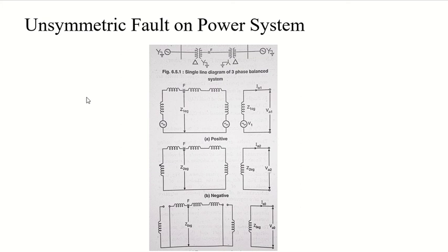All the faults we have discussed till now, I mean till the previous lecture, are easily analyzed by using Thevenin's theorem. This Thevenin's theorem is used to determine the changes in current and voltages of my linear network because of any addition of impedances between two nodes. So see the first figure which has been drawn here, figure 6.5.1.